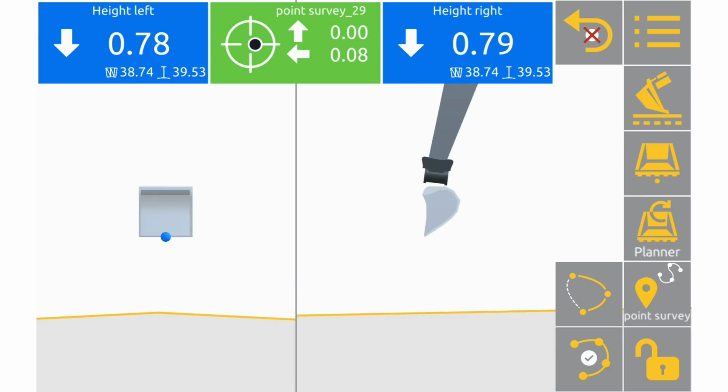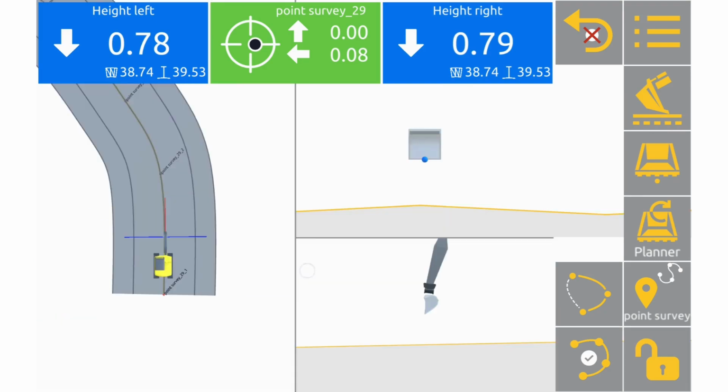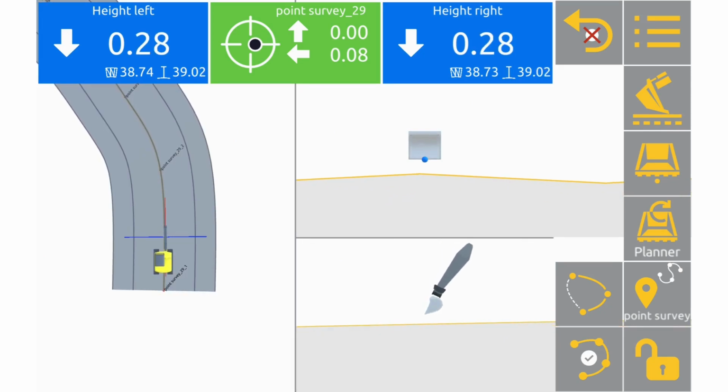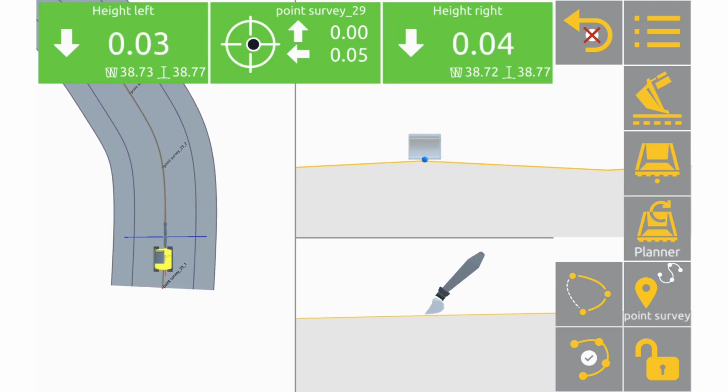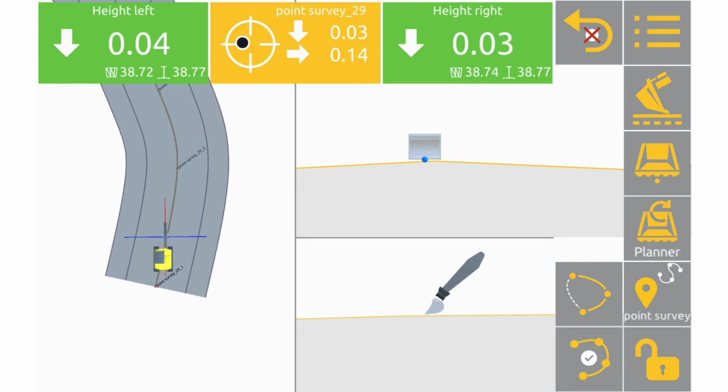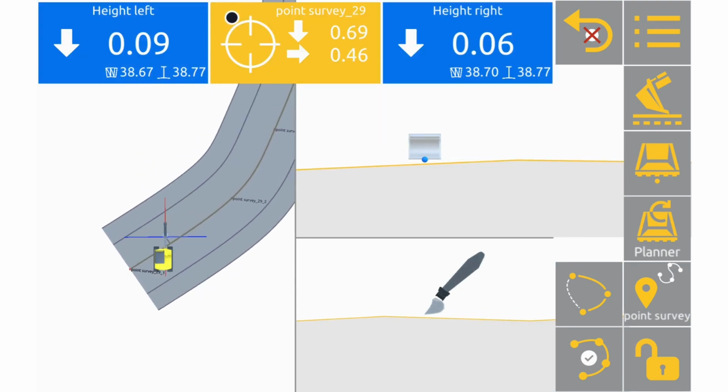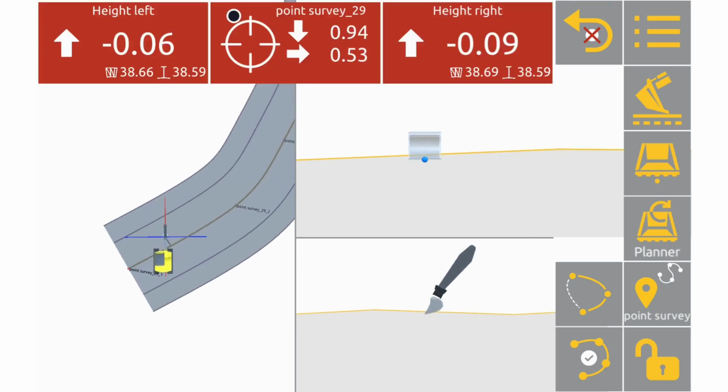Just going to change this to the two views, and you can see I used my 3% there to just show the camber that is put on it. You can see here that 30 mil per meter at 3%, because this bucket here is a meter in width, so our 3% looks to be true.